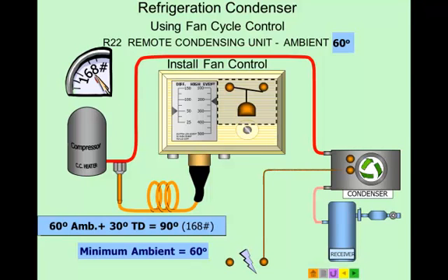Now here we see the wiring going to the fan. Normally the wire comes directly to the fan so that when the compressor is running, the condenser fan is operating as well. But we need to rewire the unit. And we're going to take one of the wires coming in, the hot wire coming in, go through the switch, and then go to the fan. So now the fan control, the reverse acting HPC, is in control of the fan.